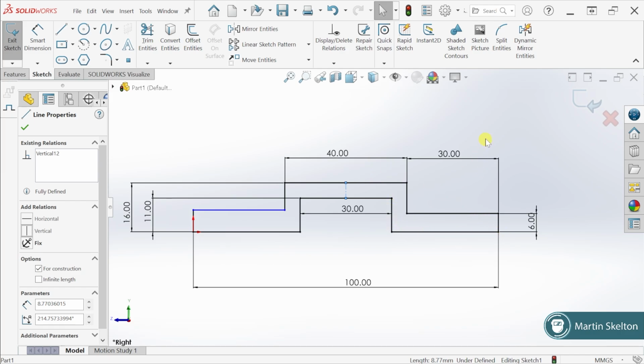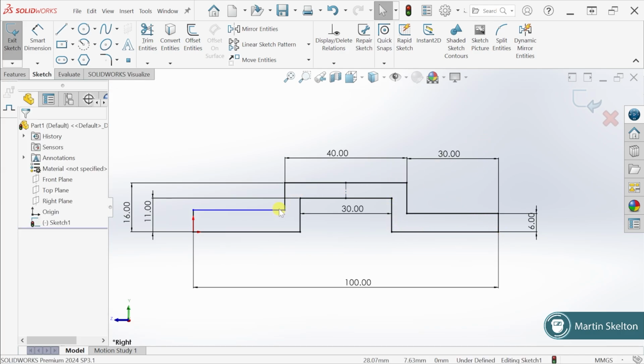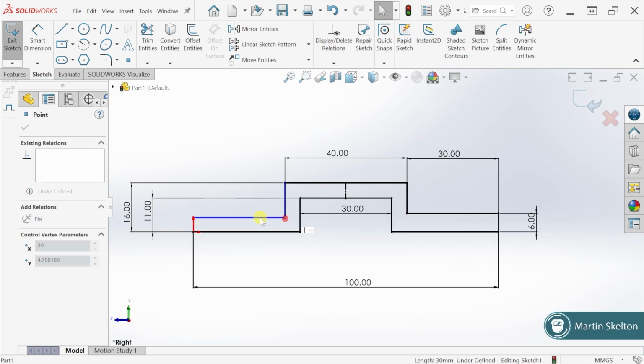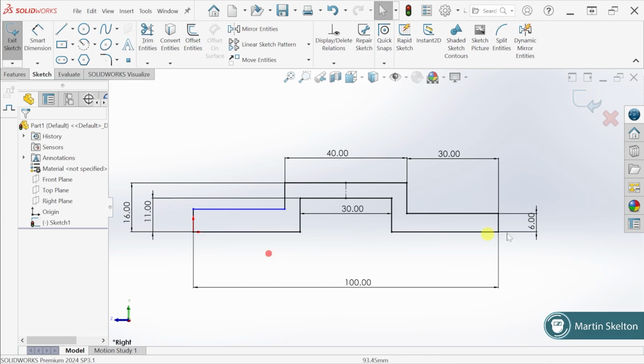So once I have it locked in place, wait there, I'm still underdefined. Everything here is black except this line. Why is this line blue if the rest of it is black? The likelihood it's missing a relation. Catch my line, drag it up and down. Yes, it's missing a relation. Can I drag it back and forward? No. So the relation that it's missing has got something to do with the height.